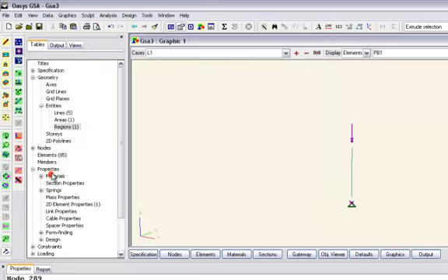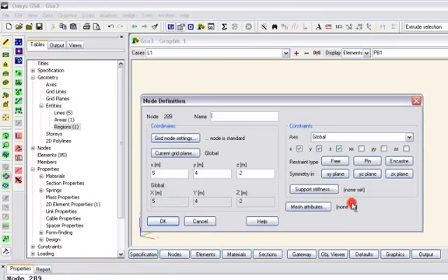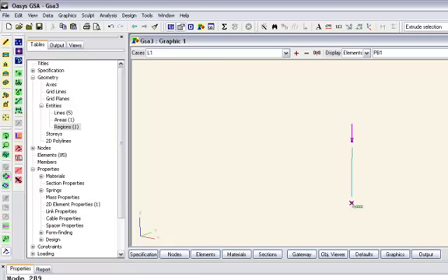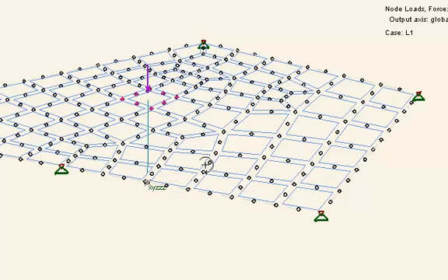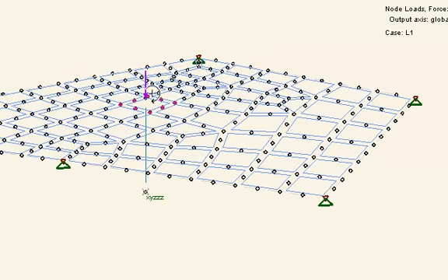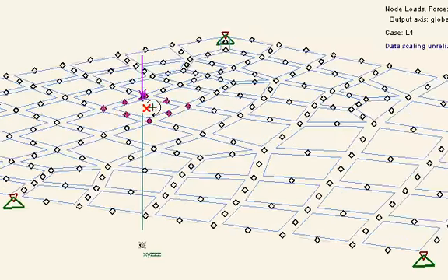A straight pin is not going to be enough because the 2D elements have no ZZ stiffness or drilling stiffness, so I will still need a ZZ restraint on that bottom node. Now this will work as a support point, even though that top end of the column is not directly tied into the mesh.